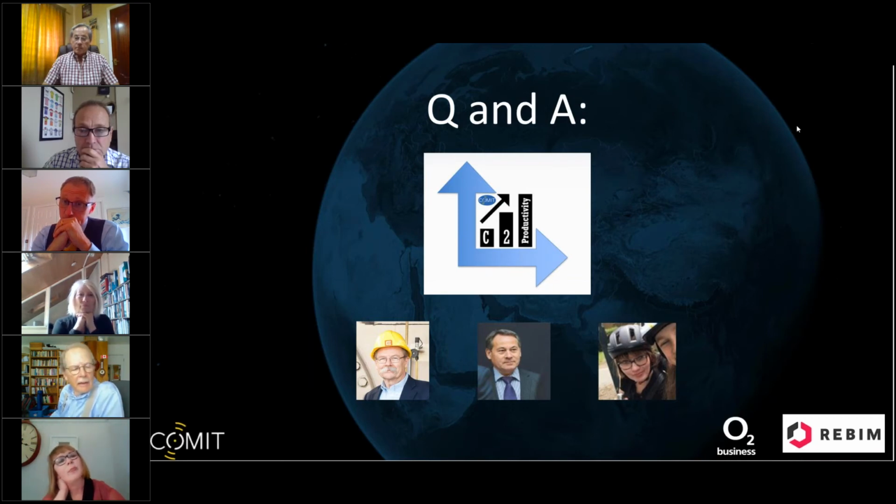Okay, I can start off on that. I think it really comes down to looking at existing data and looking at new data. I mentioned Singapore. I could mention some other jurisdictions that are mandating that anything that goes in the ground has to be captured in 3D to centimeter accuracy. In other words, it's mandatory. Singapore is a good example. If you put anything in the ground, before you close the trench, you have to capture it to centimeter accuracy. Everything new. So that means over time, you're going to be gradually building up 3D models.